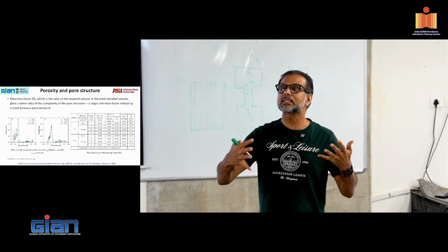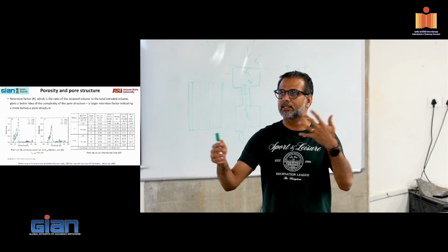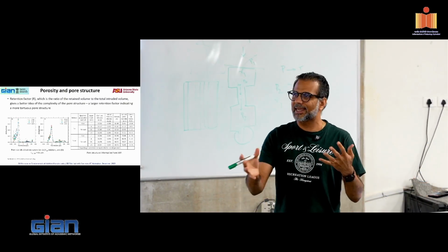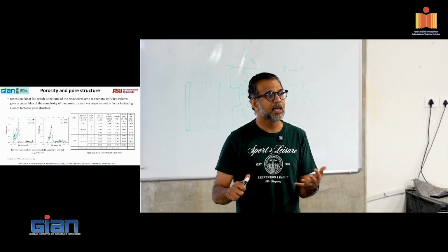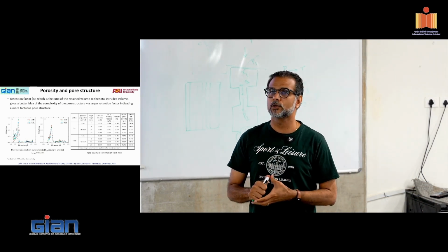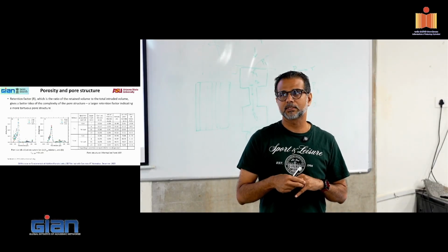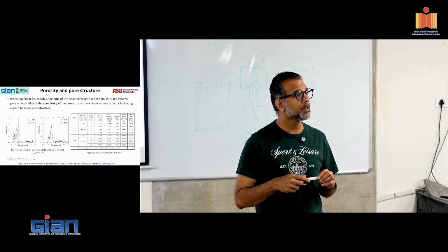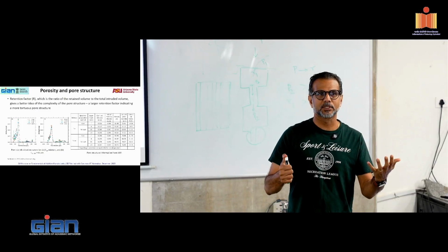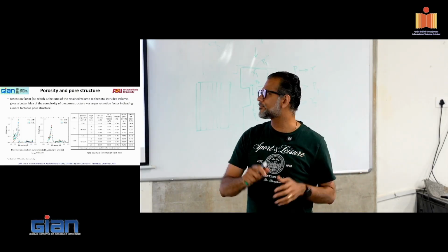You are getting representative pore sizes. There are ways in which you take the pore size diagram, take the derivative of it, take the first peak and say that's a critical pore size. So you can get some representative pore sizes, but never use it for pore size distribution. You are going to be wrong. There are beautiful papers written as to why pore size distribution using MIP is not a reliable quantity. But total porosity, perfectly fine. Critical pore size, one indicator of what a certain threshold pore size is, fairly reasonable.